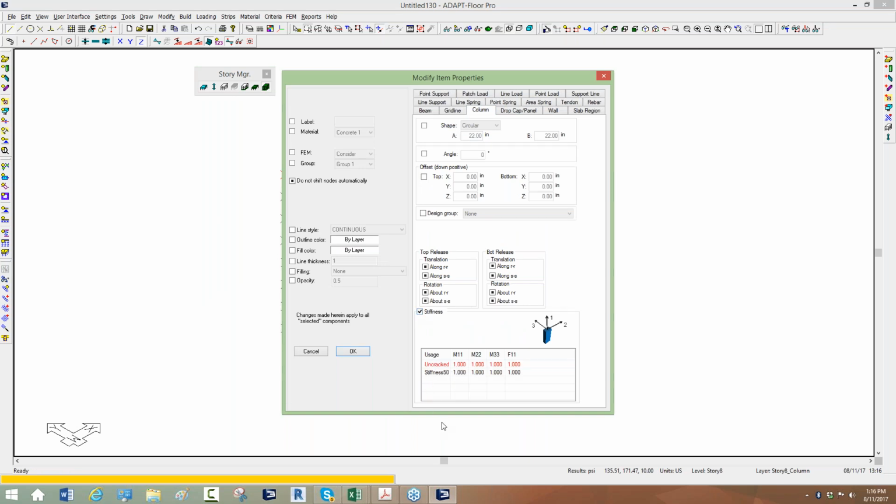The nice thing is the program retains the reactions in walls and columns for every usage analysis case that's been run. So if you did 5 usage cases, you technically could recall those 5 sets of reactions for a rerun of a single level in any model. And there's a way to purge the reactions, but by default the program will automatically retain the reactions for any usage case. So here I'm just going to set these all to 0.5, just kind of arbitrarily using a value for columns. I'll leave the S11 at 1. Flexure and torsion I'll set to 0.5.